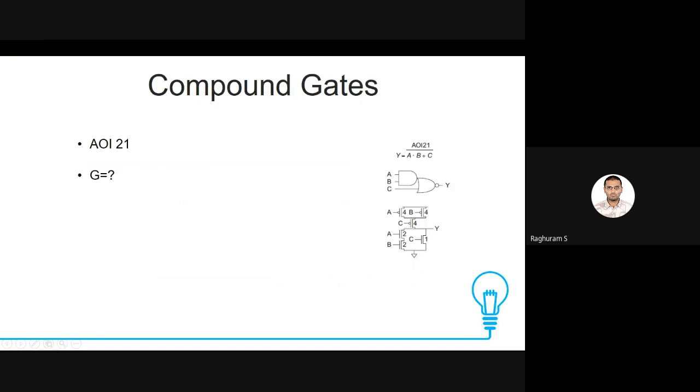So let us look at the first of these gates, and already we see some complications. So we'll go through it step by step. First question is the implementation, and generally, like static CMOS, this is also a static CMOS family itself. It's just a type of gate. Like a NAND gate belongs to static CMOS, a compound gate also belongs to static CMOS. So just like any static CMOS gate, the first thing is the functions are naturally inverting. So you see that automatically we can implement the function only with the complement on top. If I want the non-inverted function, I have to add an inverter.